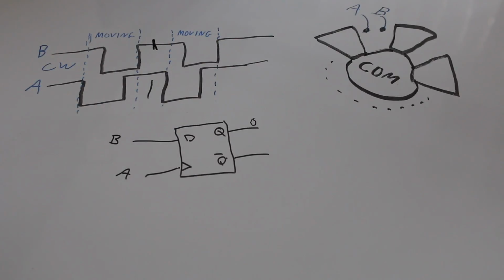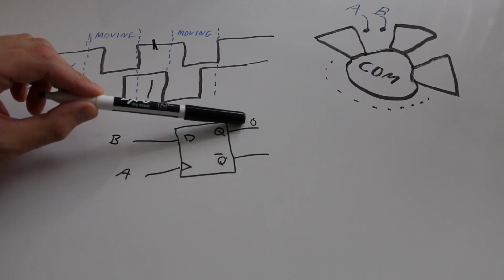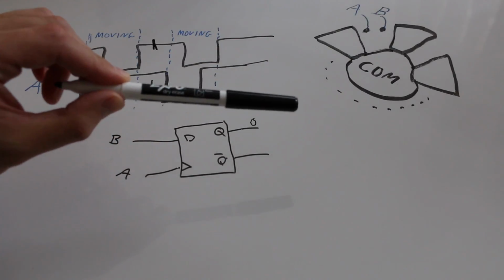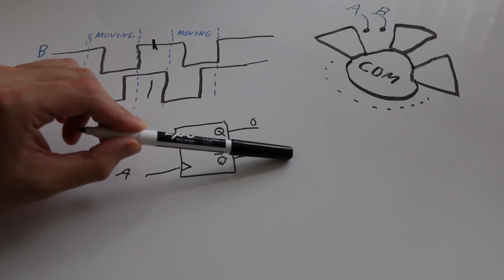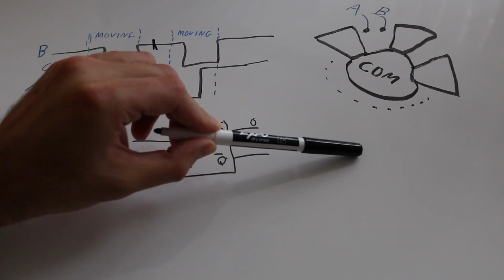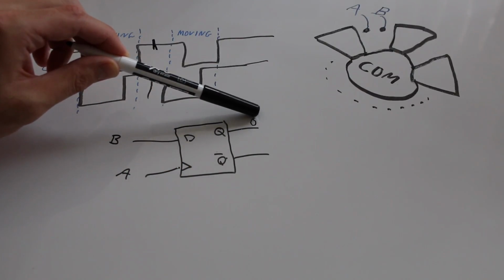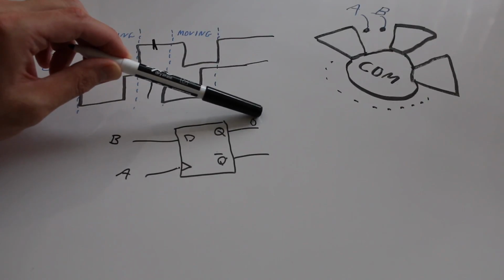So that might have some use, but what if you actually just want a circuit that will generate its own momentary pulse if you're going clockwise, and a different discrete pulse to show that you're going counterclockwise, and only when you're actually doing it. If a circuit's looking at this, it knows what you were last doing, but it doesn't know when.